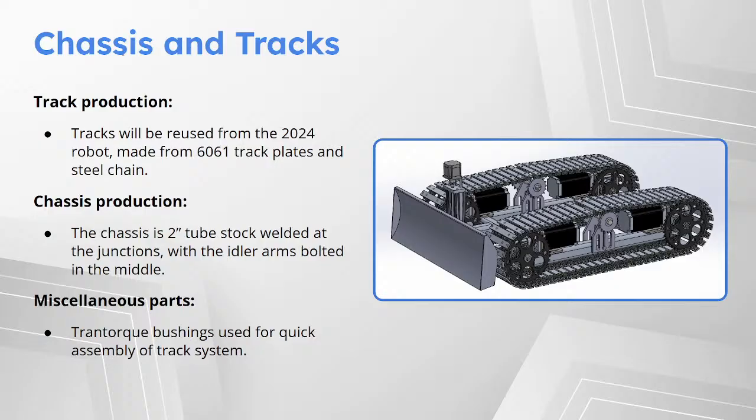I'm just curious, what systems or mechanisms do we have in place for the linear actuator to make sure it doesn't get gummed up? So it's not shown in the model here, but once we're actually done building, we're going to put basically a rubber grommet over it, or a dust shield, that moves with the carriage so that it keeps dust out.